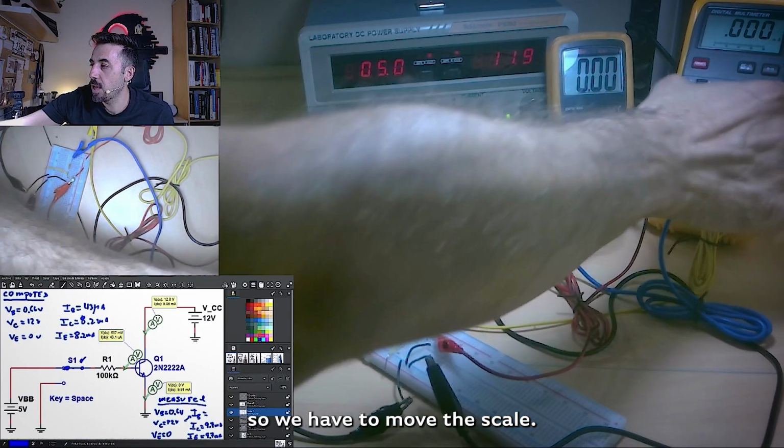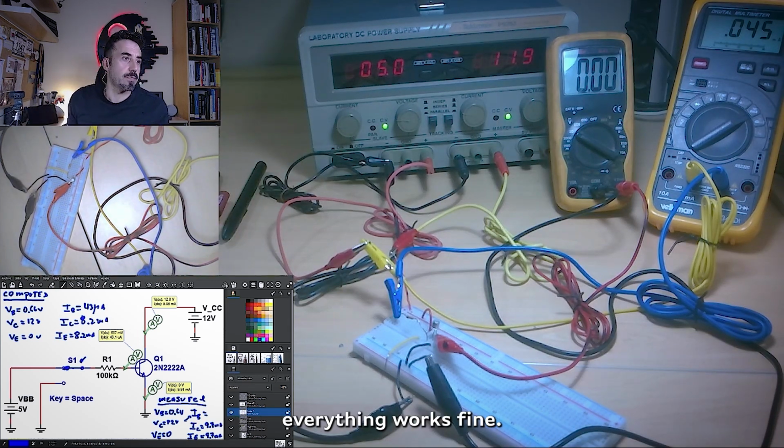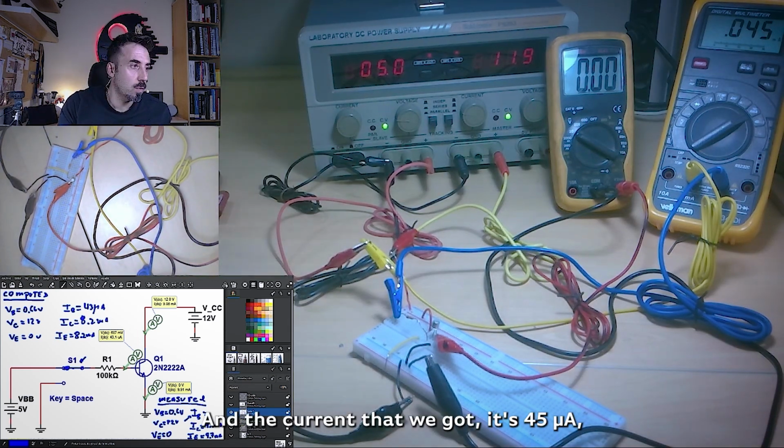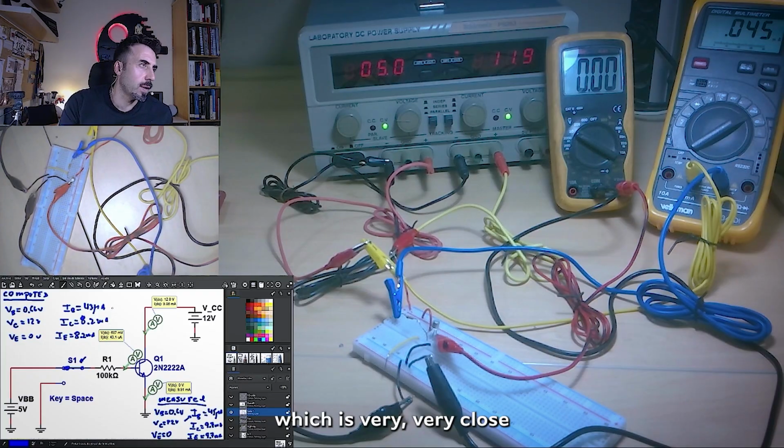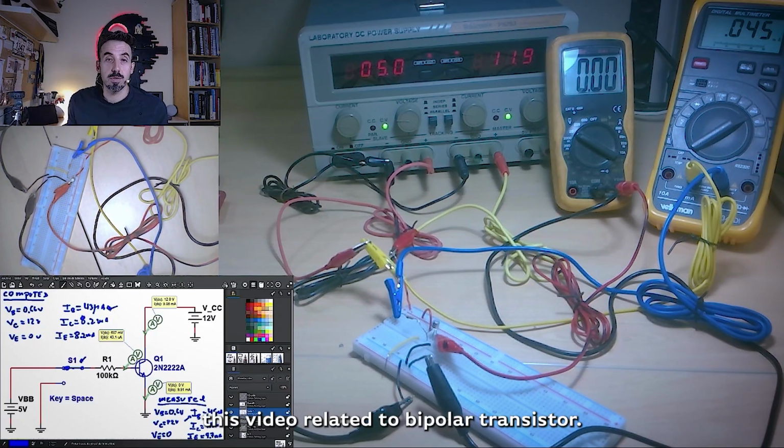So we have to move the scale. But when you move the scale, voila, everything works fine. And the current that we got is 45 microamps, which is very, very close to the one that we computed, that is 43 microamps. So everything works as it was expected.